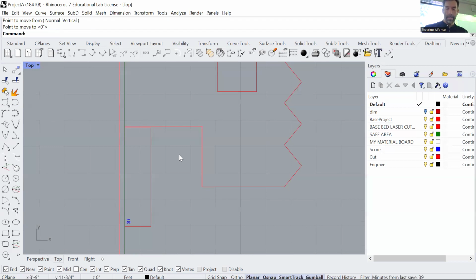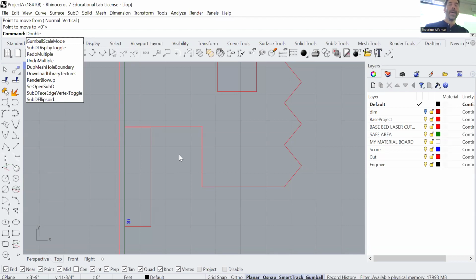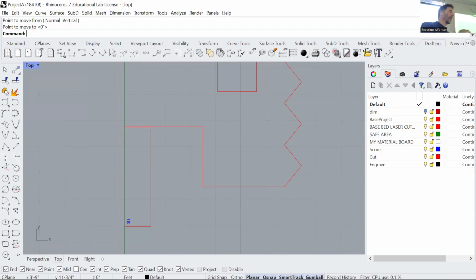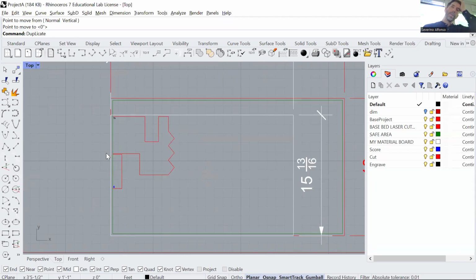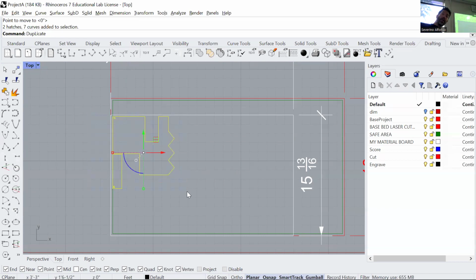I think you can detect doubles. I don't know if there's a command, but I can look at this carefully and remind you later on what that command is. I think it's in Rhino, in AutoCAD it is kill duplicates or duplicate. Let me see. Extract duplicate mesh faces. Anyway, I'll let you know. I know there's a way that you can. Oh, I know. The only way is actually doing a make2D. It sounds weird, but you do a make2D of the drawings, and what it does is eliminate those 2. I would just probably be careful in the process and start selecting the different drawings.